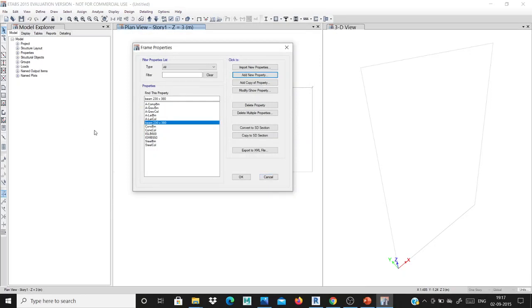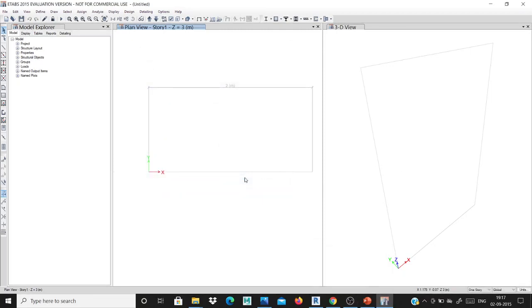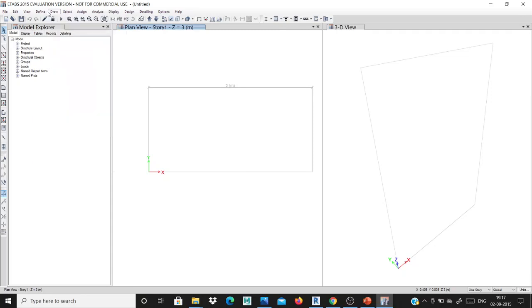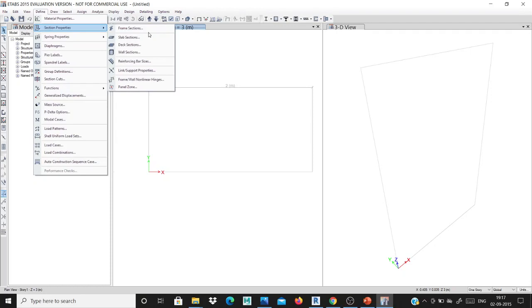In our second step I simply created the beam size for my cantilever beam. Simply click OK. Our first step is the grade and material, and then the second step is the steel created for your shapes, then material, frame section. Then the third step is to assign your beam shape. Okay, how to assign your beam shape and sizes for your material.